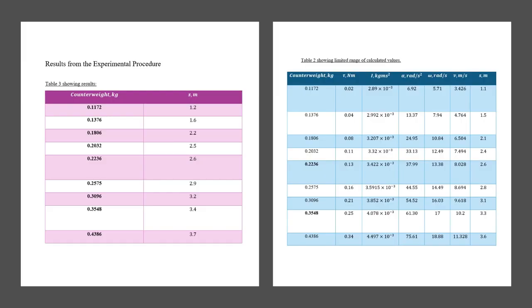Lastly, we have some tables that we obtained during the building and testing of our project. Upon experimenting with theoretical values, it was found that the distance achieved was off by 0.1 meters. So this may be due to friction, air resistance, and dynamic behaviors during launching that could be vibration, oscillation, and nonlinearities. So this may not be fully captured when doing a theoretical model. And lastly, the difference in the counterweight's mass distribution, release mechanism, and positioning can also impact the energy transfer to the projectile. With all these contributing factors, this is why the distance achieved was slightly different.